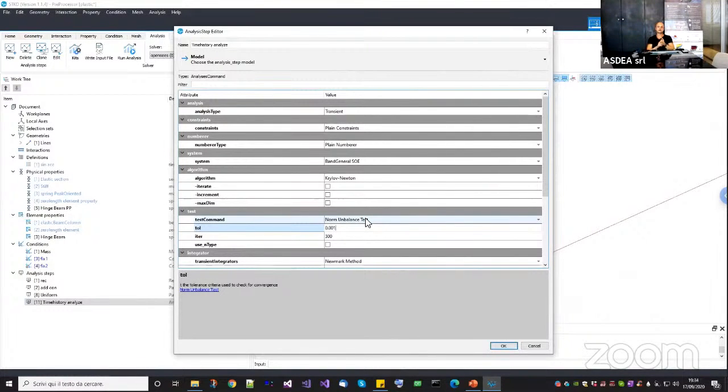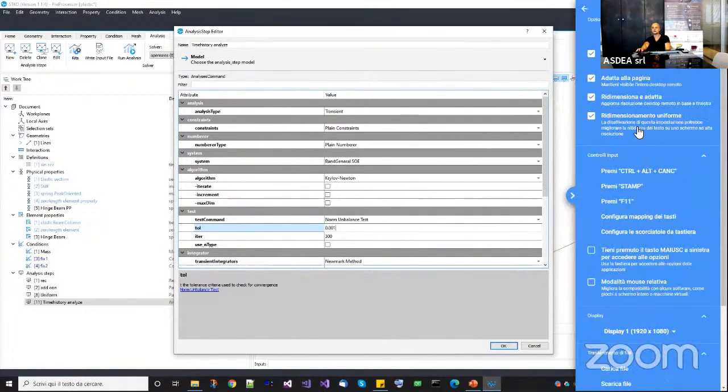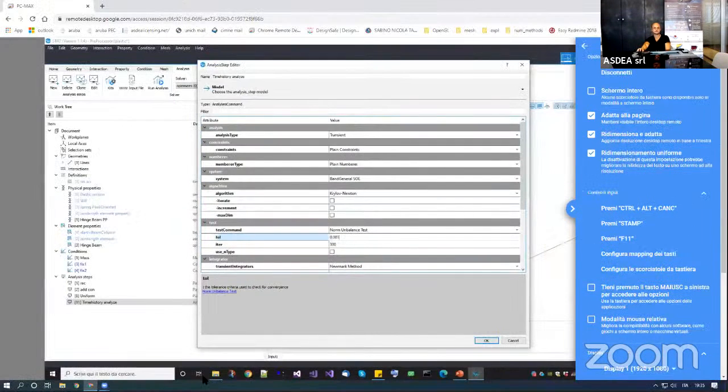When you also have rotations and moments in the same vector, you have different quantities. So this should be small for both forces and moments, not only for one of them, which is the error I made before. When I said 1e-6 meters is fine, I forgot that in the same vector I also had rotations. So this is the main way to understand how to choose those values.